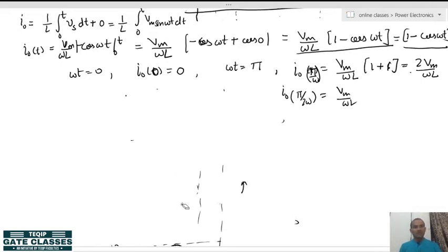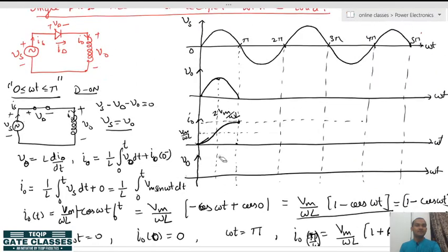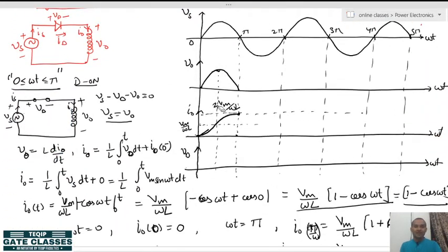Okay, now let us talk about another instant. We have already gone through the 5th step, analyzing the waveform mathematically. The next step is the load. As per the load, we have already analyzed that the load is purely inductive, and based on that we have analyzed mathematically with equations. Now the 7th step is to draw the waveform, which we have also drawn. Now, what will be the diode voltage? Since the diode is completely turned on, the diode voltage will be 0.